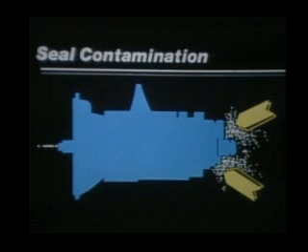The most common cause of leakage is contamination, which gets between the sealing surface of the yoke and the seal. This material acts as a grinding compound, causing both parts to wear. If the yoke is worn, just replacing the rear seal will not stop the leakage.